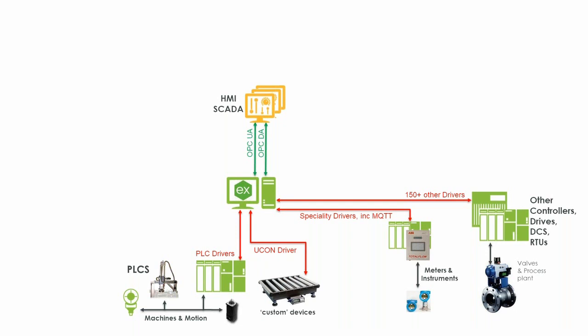You've then got a really nice little driver called Yukon, and there's a webinar specifically about Yukon later in this series. And the Yukon driver is designed to be useful in connecting the KEPServer to devices which are bespoke in nature. So black boxes that you've got in your factory that might have a COM port on the front and a manual that talks about the protocol, but you'll know it's a non-standard protocol, but you need to get data out of it. There's a way of adding bespoke drivers into the Kepware library using the Yukon driver.